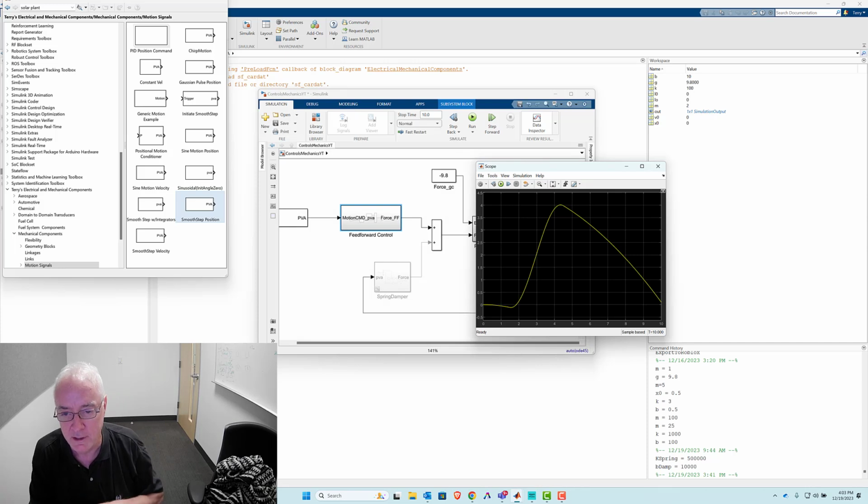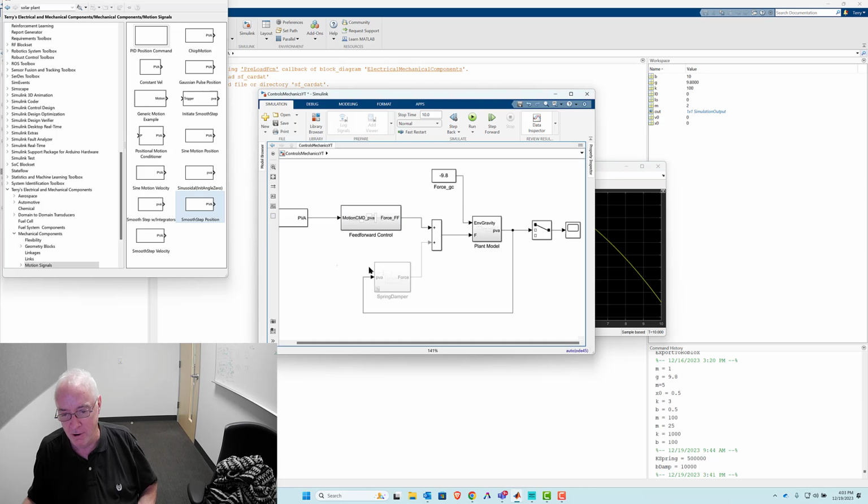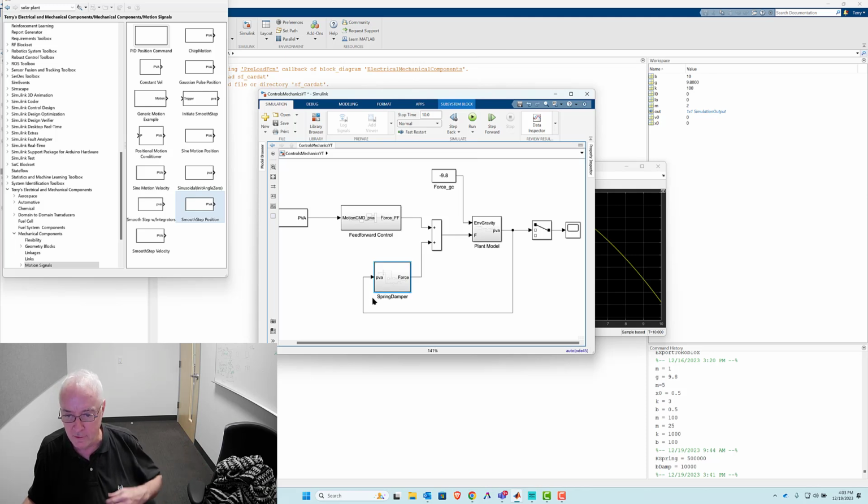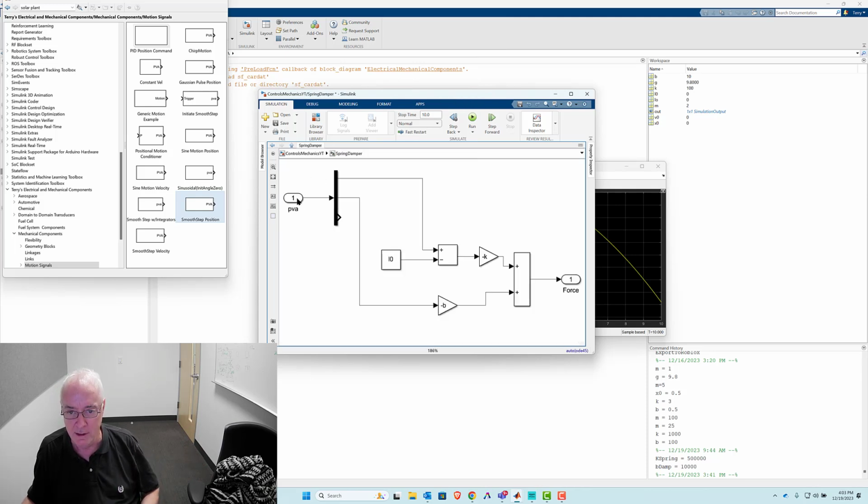Okay, and so again, it's this idea that our information is really good, but it's still off just a little bit. And being off just a little bit means that with this approach of feed forward, you better be careful about it, right? So what's the correction? The correction actually is a spring damper, and they don't call it that. So we're going to get into this a little bit here, and we'll bring this back. What it's really called, in this example, will be a PD control, right? And so I'm going to begin by going in here, and I'm going to name that